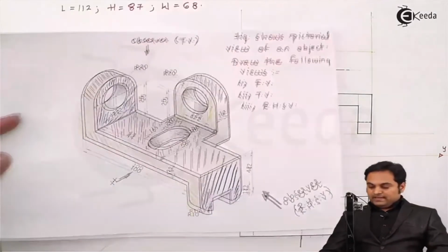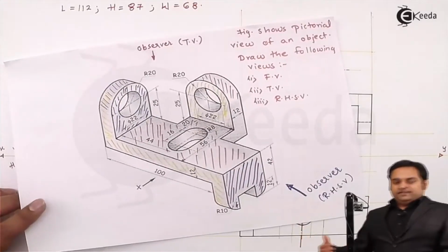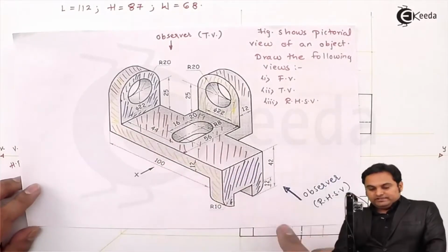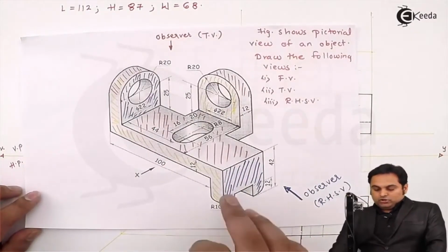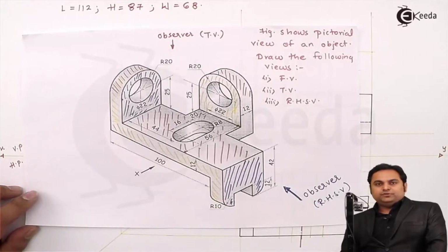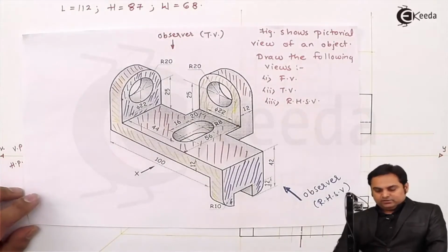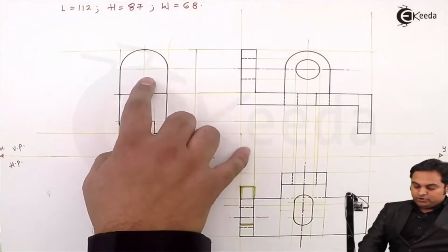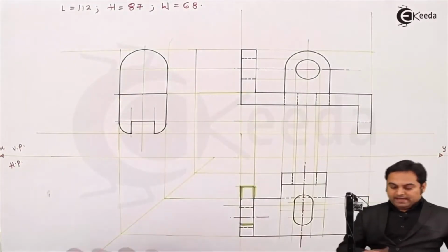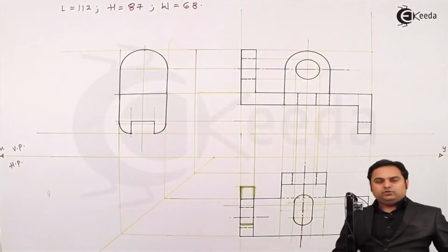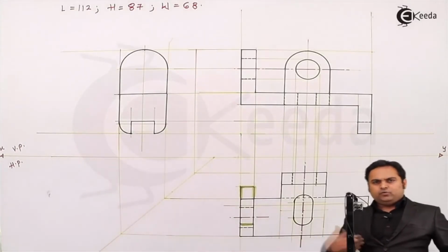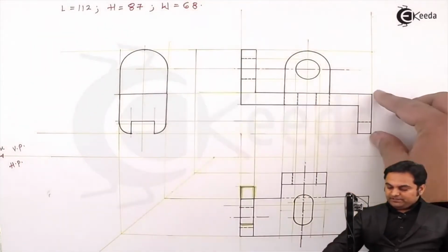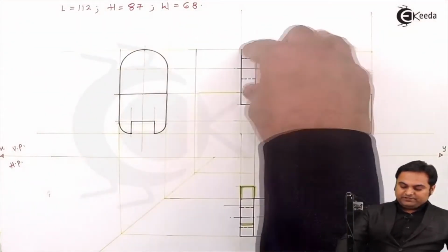So as we see here from the side view, both these surfaces which I have shaded blue are on different planes. So between them there should be a dark line. Here, as we see, there is a dark line in between them showing the change of plane. Which surface is ahead and which is behind, we can see from the front view: the bottom plate is ahead, the semicircular plate is behind.